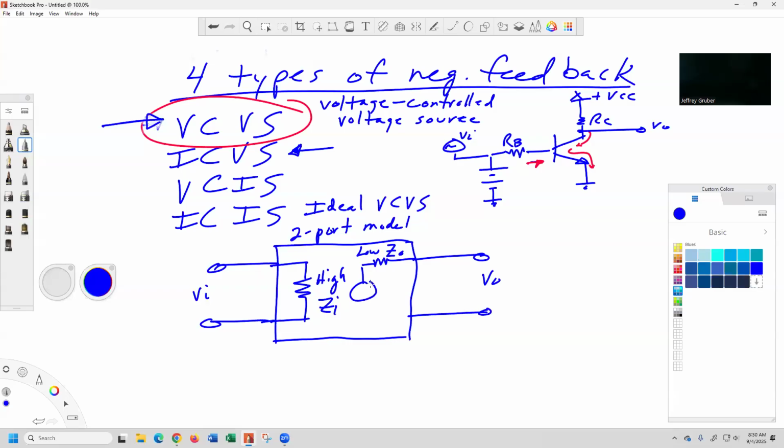For what we're dealing with, sometimes you'll hear me say input impedance, output impedance. Impedance is everything: resistance, inductive reactance, capacitive reactance. For what we're dealing with, it's input resistance, output resistance. We're dealing with an op amp. There's no inductors. At very high frequencies, everything is an inductor, a capacitor, and a resistor, and there's no such thing as a pure resistor. We're not dealing with real high frequencies. So our operational amplifier, that 8-pin chip I showed you, it's just input resistance, output resistance.